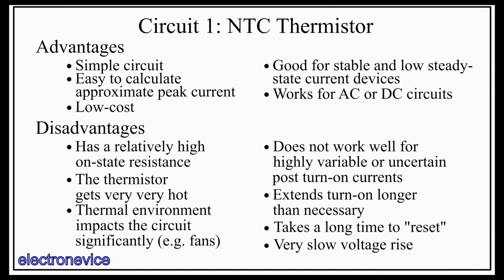The dissipated power has to go somewhere, which causes the thermistor to get extremely hot. When I was running these tests, the thermistors gave off the smell of burning plastic at max current because they were so hot they were outgassing whatever residues were on them. Not only off-putting and causing burns if you touch the thermistor with bare skin, the high heat and the fact that the resistance decreases the hotter it gets could result in thermal runaway causing a fire if a mistake is made during the design process and the thermistor is too close to something flammable.